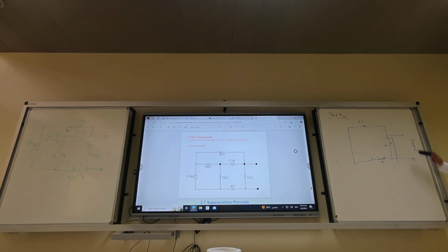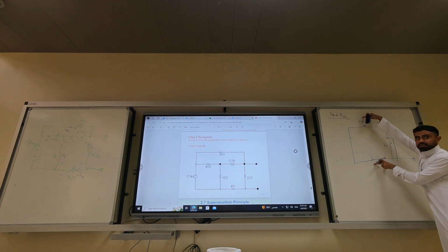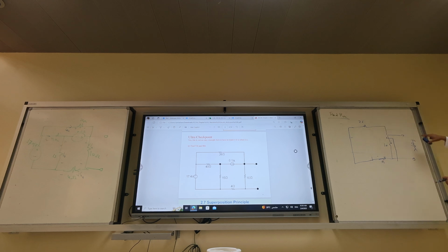2 sections, so you have 4. What will happen here, in the eyes of Thevenin, is 10 in series with 4? No, he does not see it as series. Remember, this is a closed square. So in the eyes of Thevenin, he sees 10 in parallel with the 4 and 26. How? Because he is measuring the resistance this way. So this is 10.